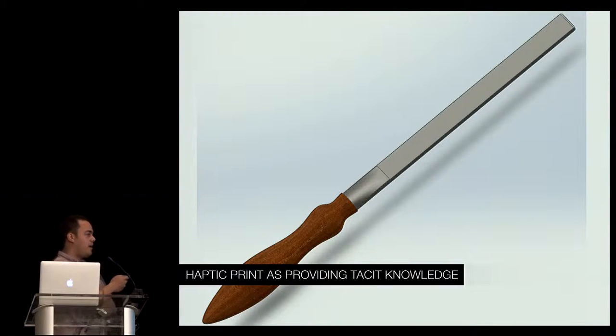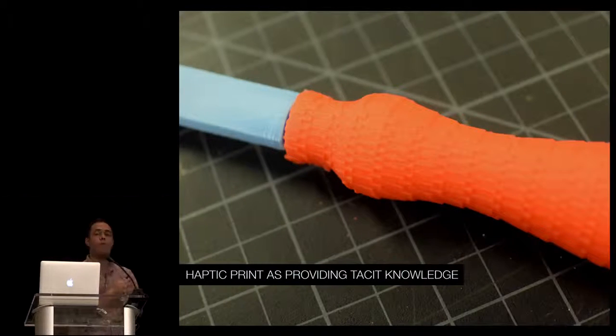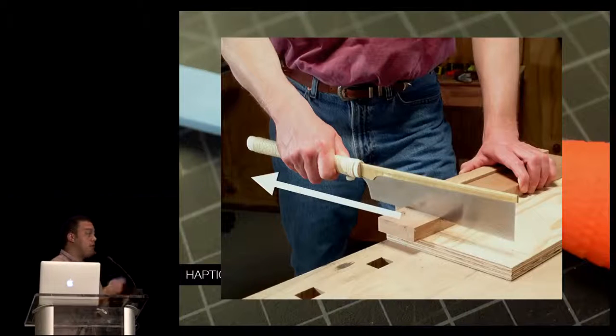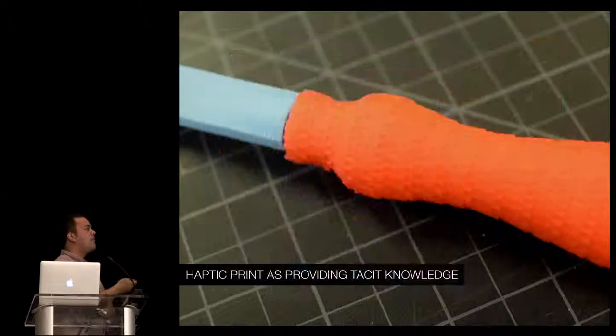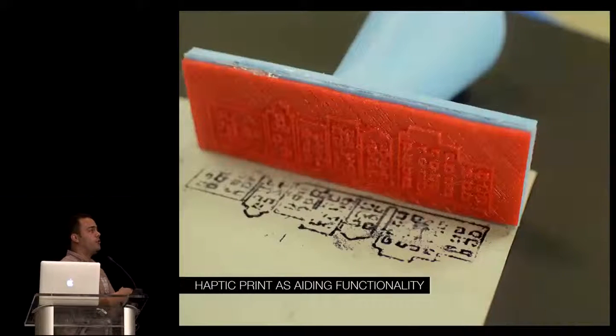When we applied the techniques that we developed with HapticPrint, we were looking at ways of conveying more tacit knowledge through these textures. For those of you unfamiliar with files, files are only supposed to be used in the pull stroke. And so in order to convey that, we developed this sawtooth texture. That sawtooth is abrasive in one direction and smooth in the other. This conveys a really subtle tactile, haptic cue to the user of correct tool use.